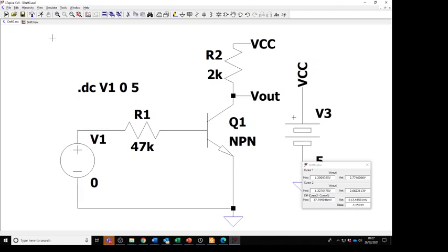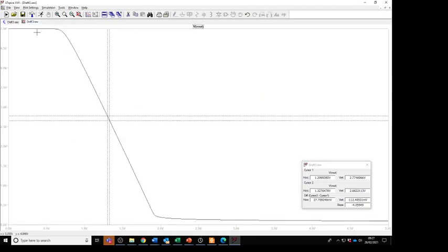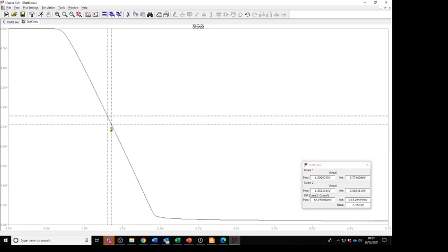What we can maybe now do is start to set it up as if it was in the bias conditions. Let's go back here. We want 2.5 volts here, and we can read off what we need at the bottom: 1.35. So we want an input voltage of 1.35 volts to put us at this position with 2.5 volts at the output.